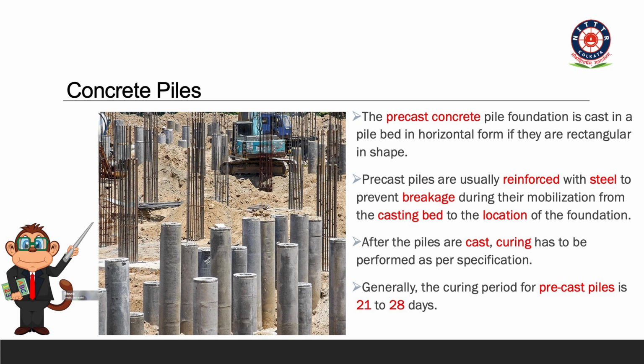So precast piles are usually reinforced with steel to prevent breakages during mobilization from the casting bed to the location of the foundation. And after the piles are cast, curing has to be performed as per the specification. Generally the curing period will be 21 to 28 days.